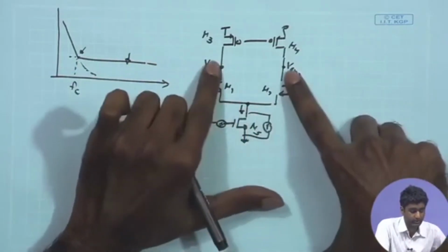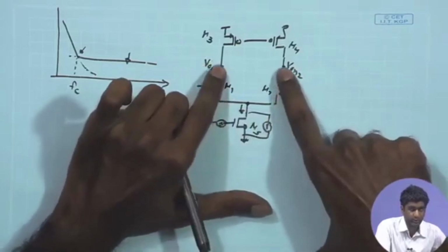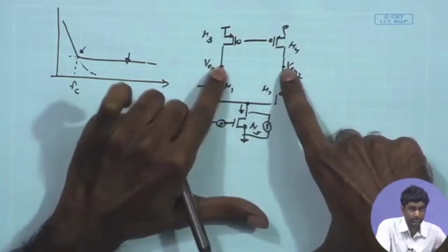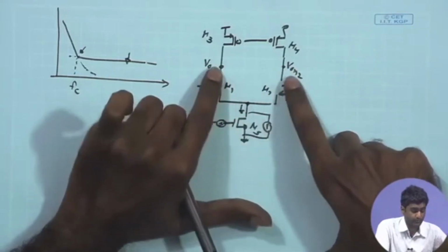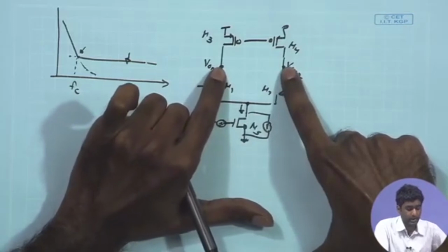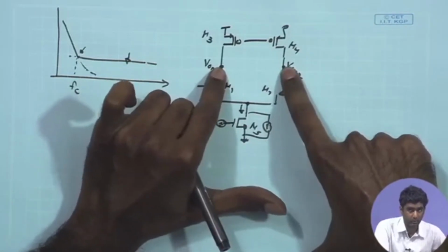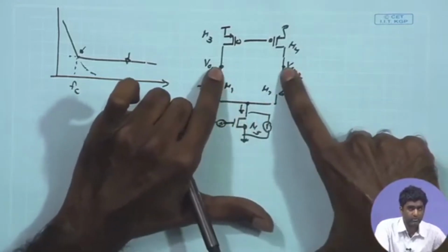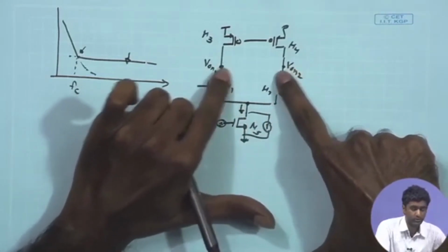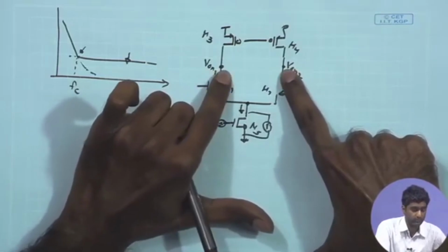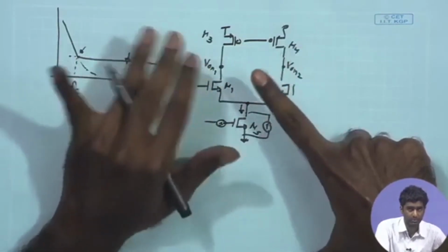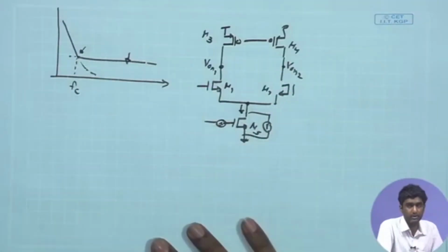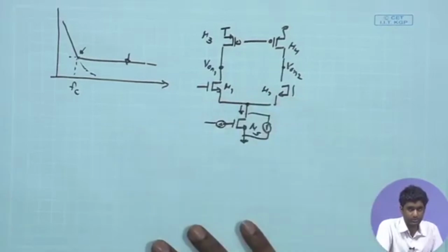Its effect is getting divided, and you are having an overall noise current flowing in these two branches and coming at the output nodes over here, and these are correlated because they are coming from the same source. So, you can have an overall noise coming in the common mode operation because of this transistor, and we are not concerned with the common mode signal so much. An overall common mode noise, which is much minute as compared to the signal, can be relatively less significant as compared to the differential operation where it is not appearing. So, this is just a small point to be noted over here.